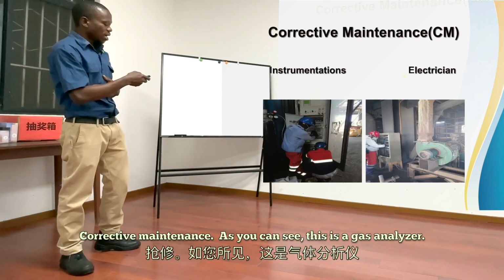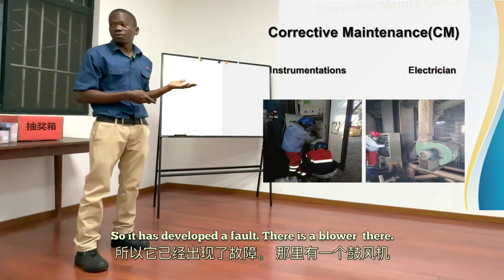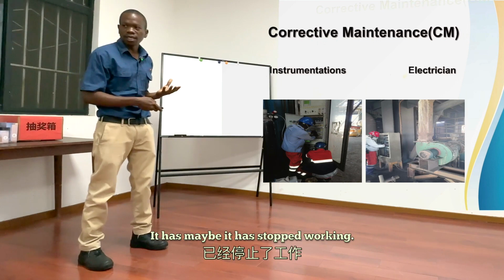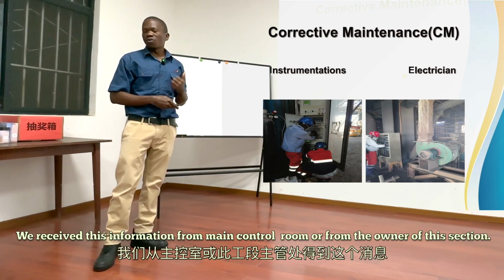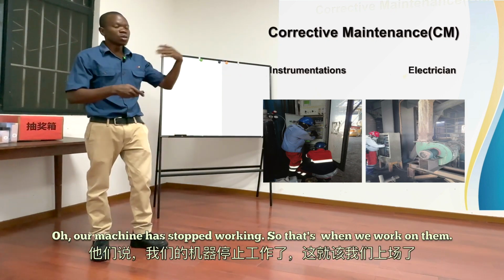Corrective maintenance. As you can see, this is a gas analyzer. It has developed a fault. There is a blower there. It has stopped working. We receive this information from the main control room or from the owner of this section, saying our machine has stopped working. So that's when we work on them.